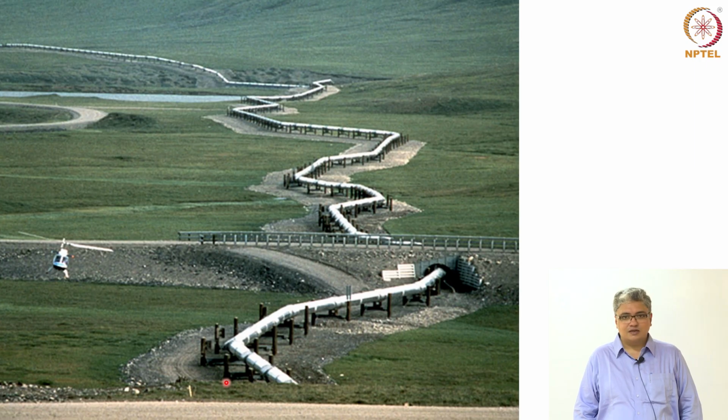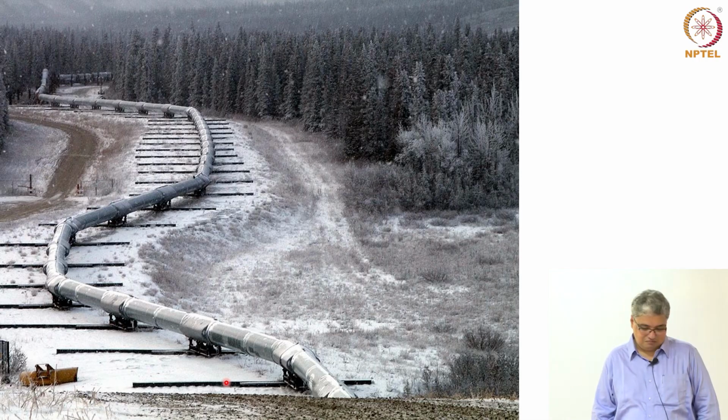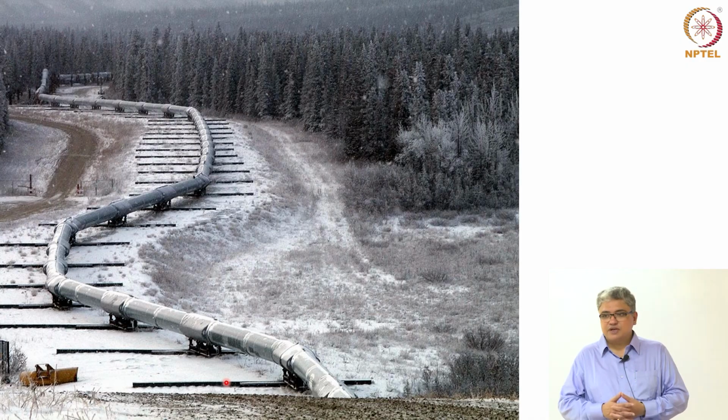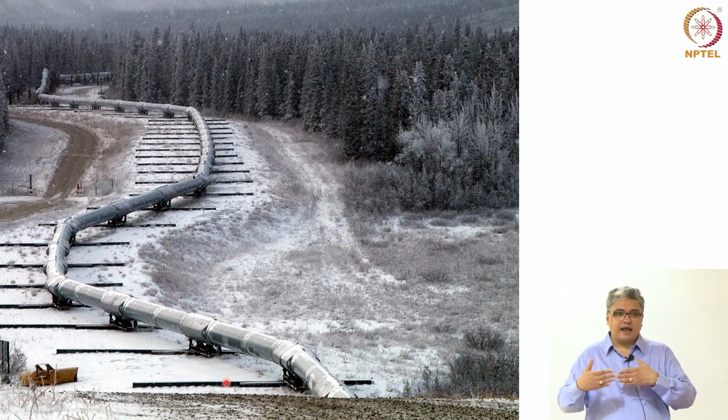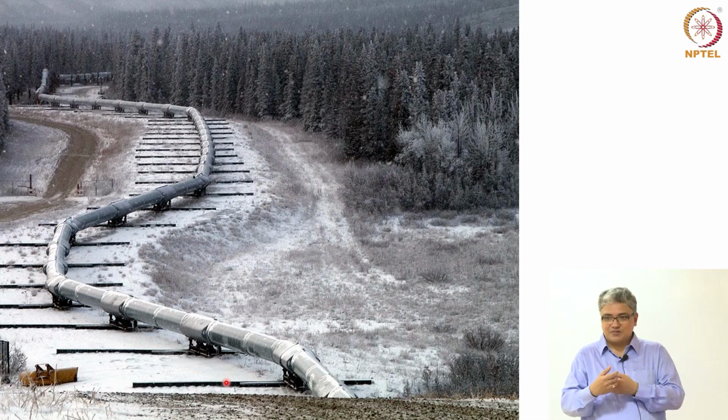This is what is called the Trans-Alaska Pipeline project to transport oil, fuel. And for this, engineers had to do a very unique innovation. So here is a pipeline, and if you see the pipeline, it's all bent, crooked. You must be wondering, why is it like that, right? And here, if you see, it is supported on something which is sitting on some rails. This is because it is crossing an active seismic fault, and so the earth moves when there is an earthquake. And if you create one stiff pipeline across it, that pipeline will break. Okay? So you create these segmented pipelines with flexible joints supported on rails like this, so that no matter how the earth moves, shakes, the pipeline stays intact.